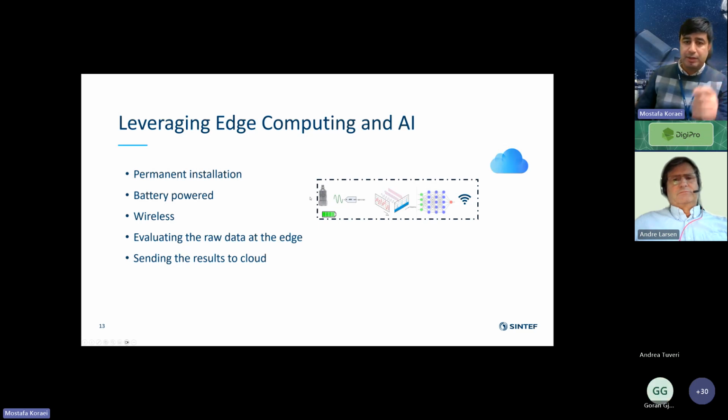It is the reason that we introduced this system that is a combination of sensor, ADC, FFT, and AI machine learning on the edge. And the good thing is that this system can get better and better by getting more failures and finding more problems in an environment. So if we have, for example, 100 similar machines like electromotors in one plant, they could have a lot of similarity in that plant, but they could be different from the same type of machines working in another plant, and this system can differentiate between those kinds of vibration and give better information or better categorization for the machines that are working in that specific plant.